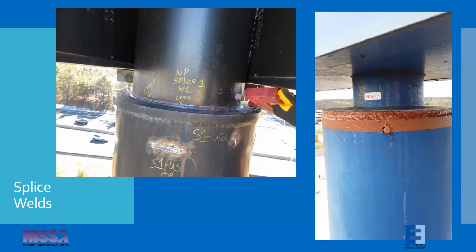The photograph on the right, you're showing a bolt that was welded into a lift hole. That's not an acceptable technique for filling a weld hole. It still does allow the chance for water to get into the inside of the pipe. And so number one, it wouldn't pass the AWS standard for welds. But then secondly, you are creating a pathway for water penetration to the interior of the pole. And you want to prevent that as much as possible.